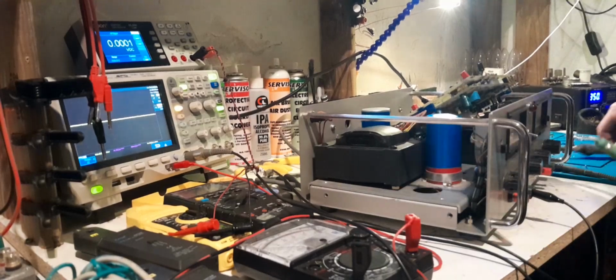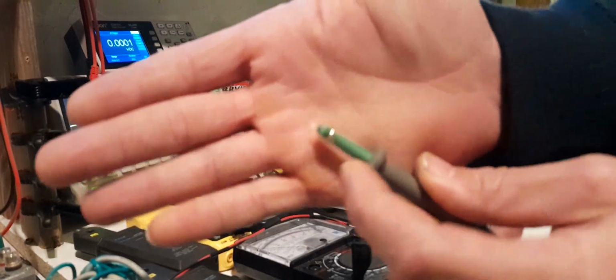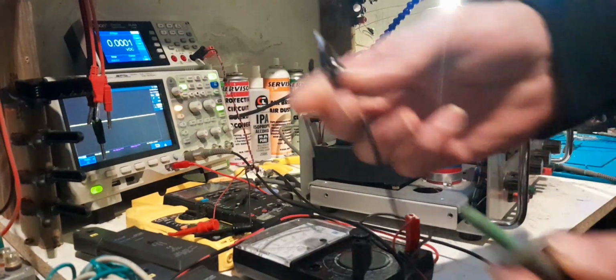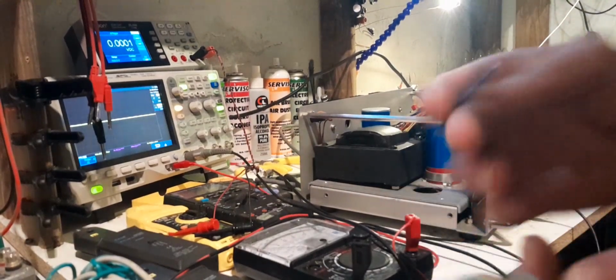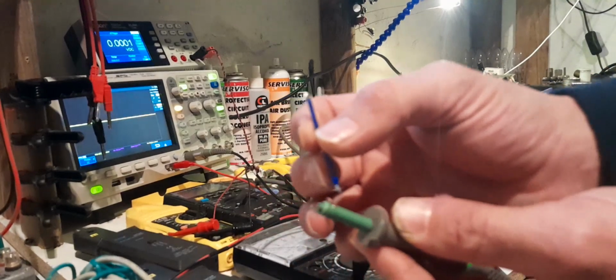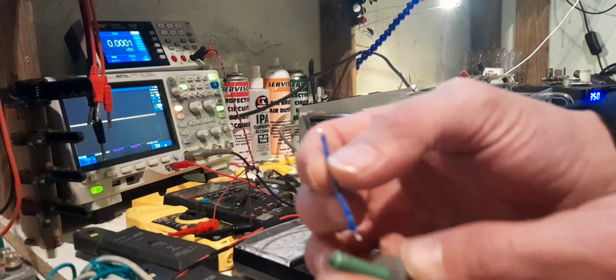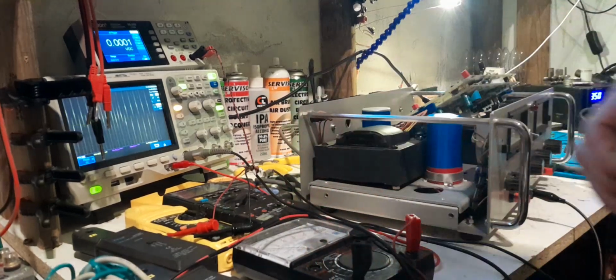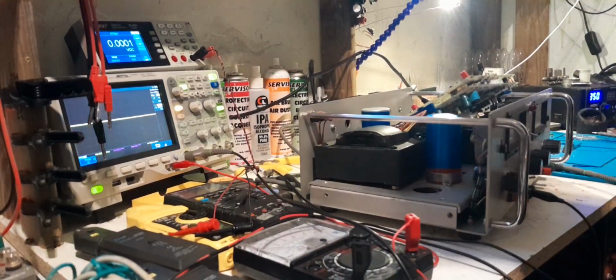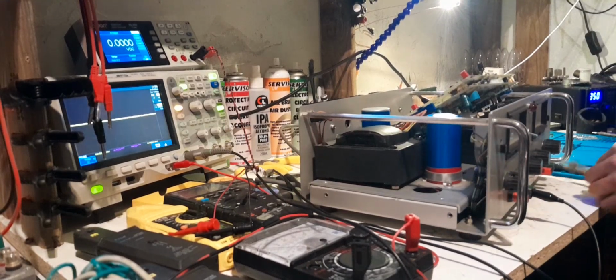So right now I don't have anything on the ground of this probe. I've just got the tip coming out because I'm using it in conjunction with this ground lead that's going back to the ground on the scope. But I also sometimes, like when I've been looking in between an op amp's power rail and its input, I've been soldering this piece of wire on here, soldering the wire to the power rail and putting the tip on the input. And like I said, in other situations, like a reference where one end goes straight to a power rail, I will solder straight across it like this. Sorry, that's not focusing.